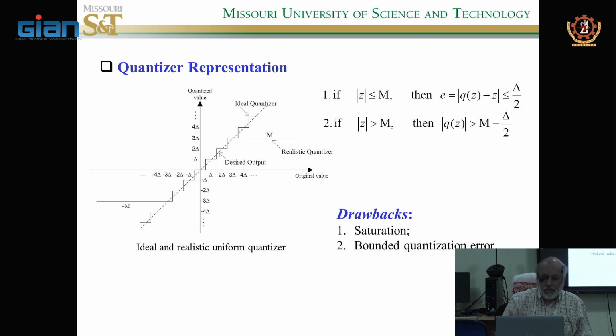Now we also will talk about actuator saturation later in the nonlinear part of it. Actuators also have a saturation. If you run a motor, let's say they'll tell you the motor runs at 1500 RPM, right? But even if you increase the voltage, it won't increase the speed. It stays there at 1500. So actuators also have a saturation effect. We'll see that in the next part of this presentation, lecture 6, where there is actuator saturation.